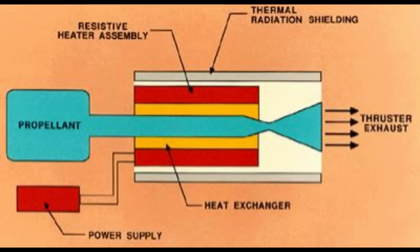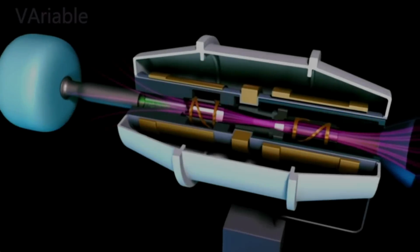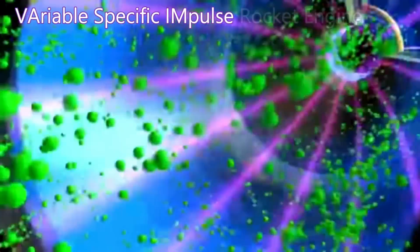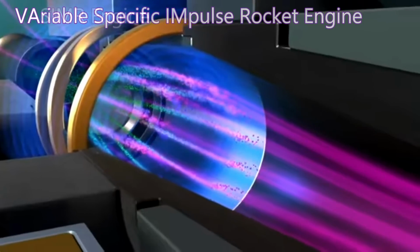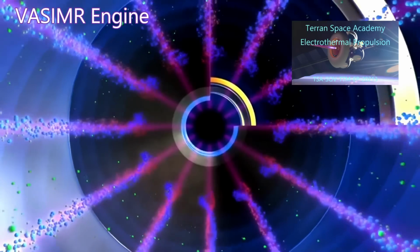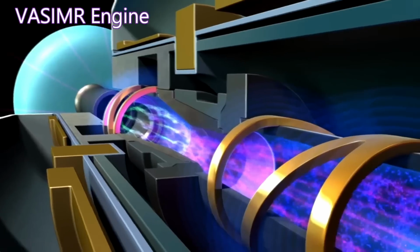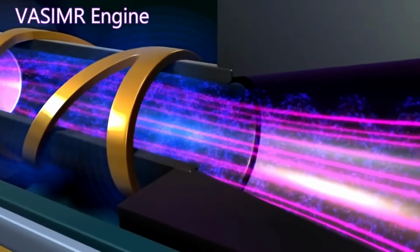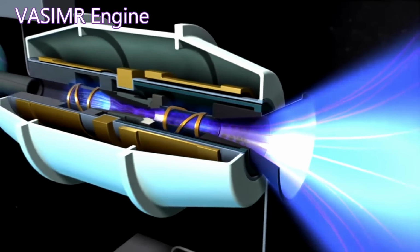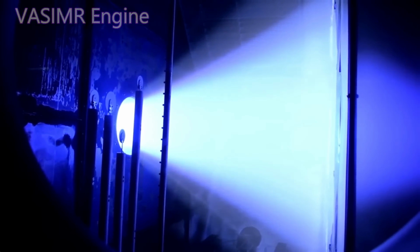Electrothermal engines use electrical energy to heat the propellant and allow its expansion to accelerate it. One of the best designs for this type of engine is the Variable Specific Impulse Magnetoplasma Rocket engine, or VASIMR, designed by former astronaut Dr. Chang-Díaz, and described at length in this lesson. The VASIMR turns a gas into a plasma so it can be controlled and bottled by electromagnetic fields. Then it uses radio waves to heat the plasma to extreme temperatures that would surely destroy any material, allowing it to expand out the back and provide thrust.